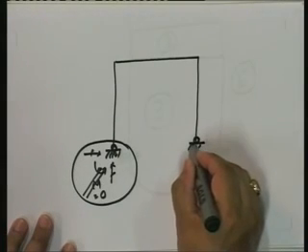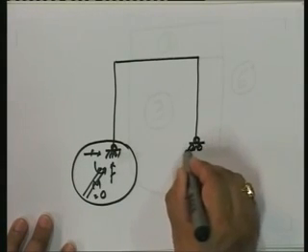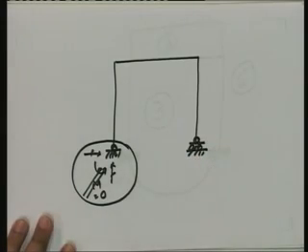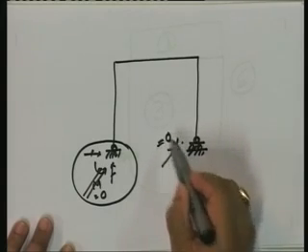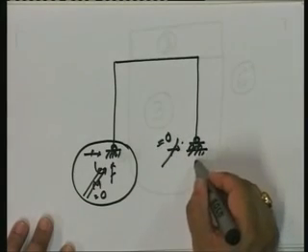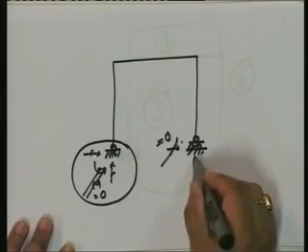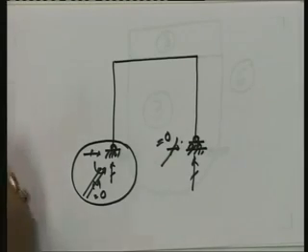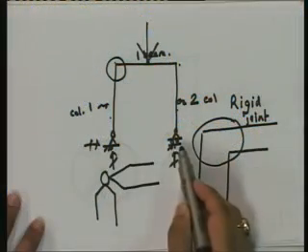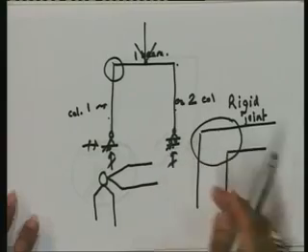I am going to allow it to move in this direction. What does that mean? That means I have taken this restraint and put it equal to 0. In other words, how many restraints am I left with at this point? Single one. Look at this structure. What does it resemble? It resembles this. Hinge support at the left end, roller support at the right end.